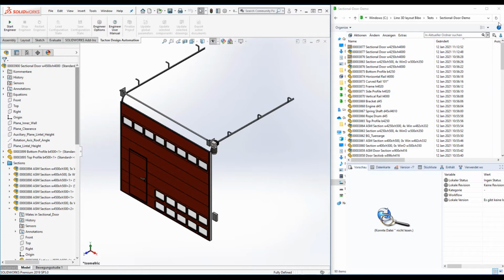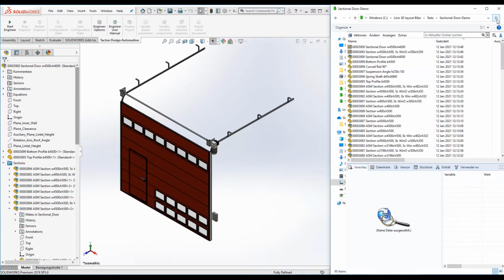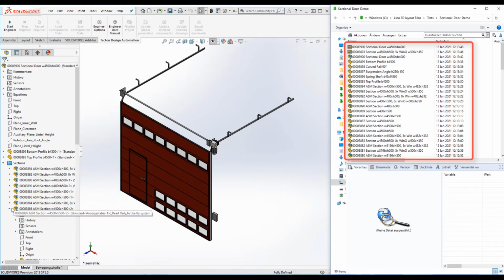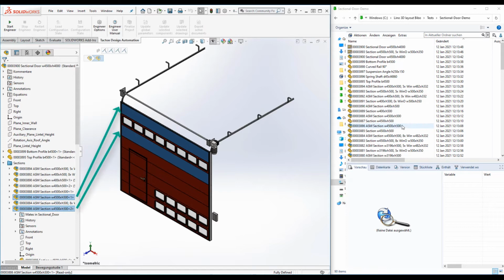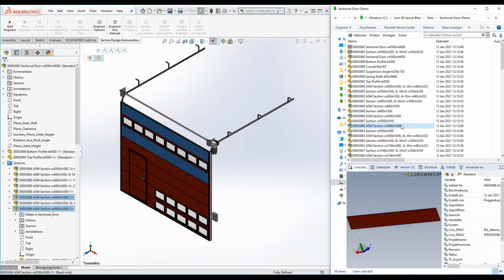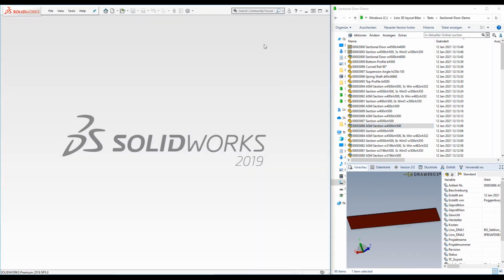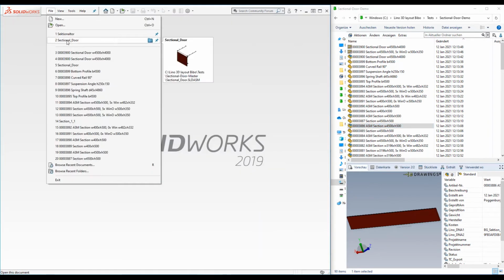We refresh the view in the PDM window on the right-hand side and can now see which components have just been created automatically. Already here we can see that we now use the same assembly 3886 several times for the sections without windows. So Lino PDM Pro has recognized that two assemblies, which were different before we ran Lino PDM Pro, can be represented by two identical assemblies, so it avoided the creation of a duplicate. We close the derived assembly now and load the master assembly again.